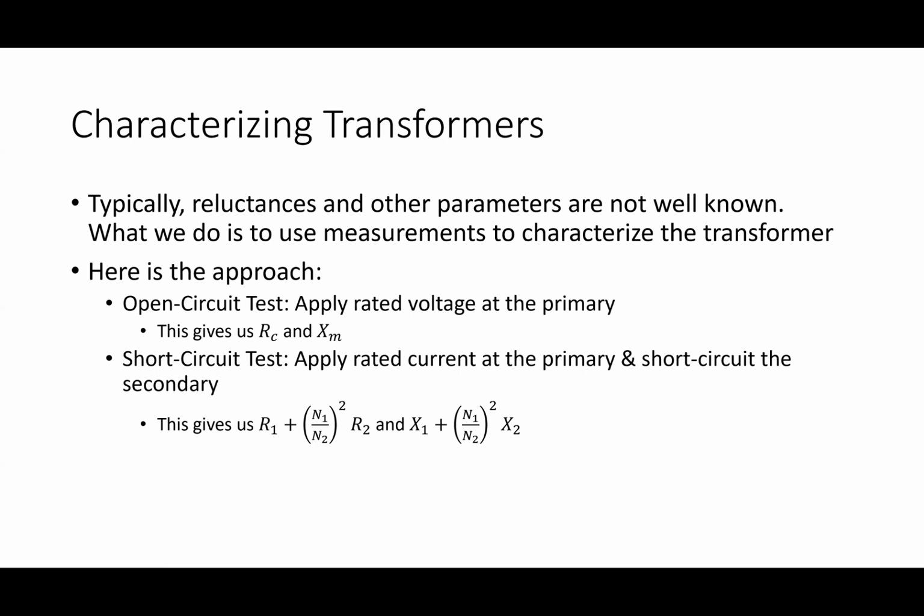So really what we usually do is there's a set of tests. If Duke or any utility wants to understand the parameters of their transformers, then they will have the vendor that they buy them from do a set of tests on those. And I talked about this last time, the open circuit test and the short circuit test.